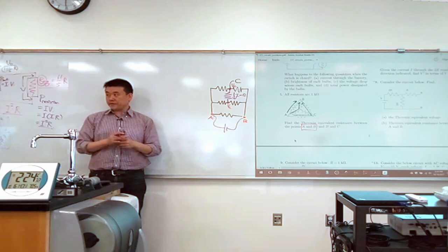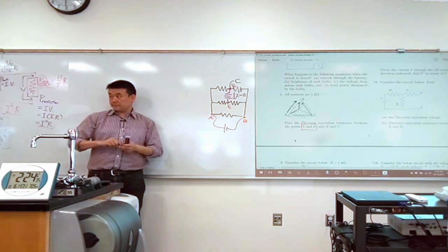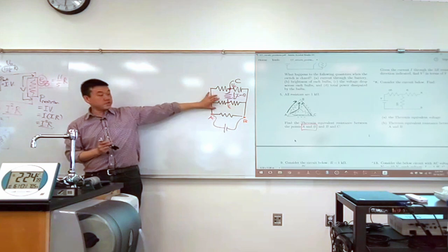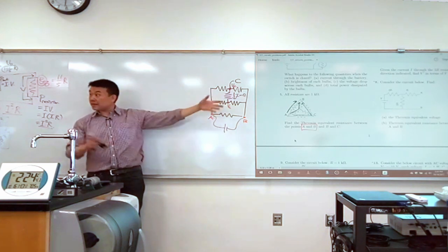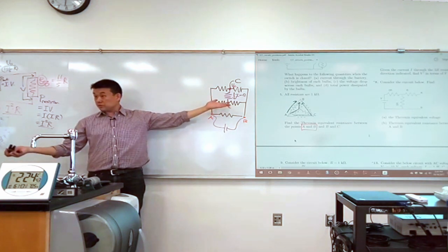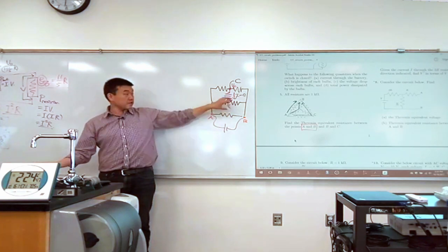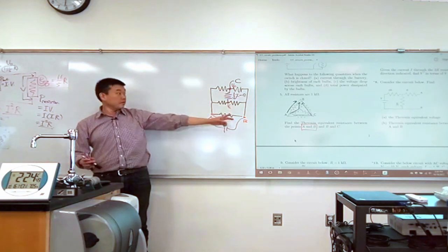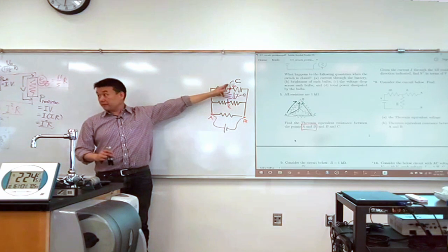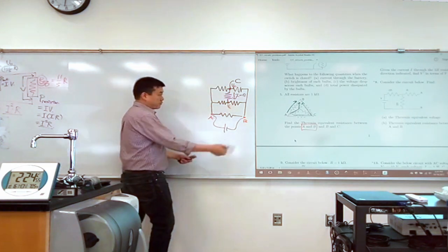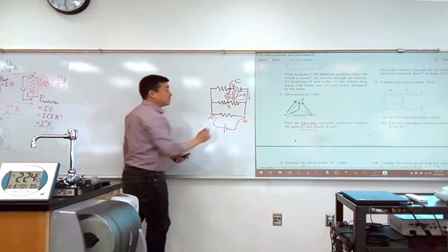Okay, can you explain the symmetry? Yeah, like these two branches. If we swap them around, nothing would have changed. So these 2 points are the same points for all intents and purposes. You can swap them and nothing changes. So these 2 voltages are the same. Once you realize that, then you can say, oh, based on the symmetry, this is true. Current here is 0.